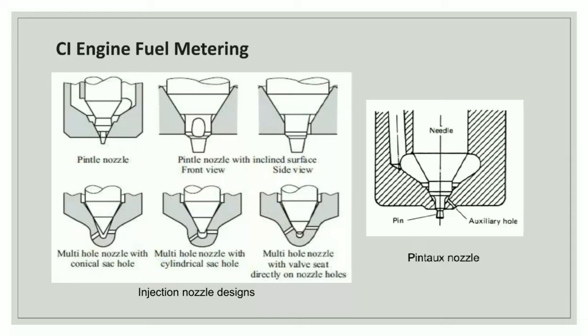Here you can see the injection nozzle designs. Pintle nozzle with inclined front view, and pintle nozzle with inclined surface side view. Multi-hole nozzle with conical sac hole, multi-hole nozzle with cylindrical sac hole, and multi-hole nozzle with valve seat directly on the nozzle holes. And on the right side there you can see the Pintox nozzle.